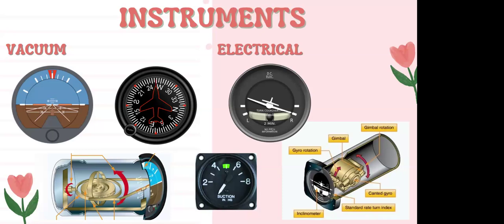So these gyros are rigid, and they're designed in a way to not fall over. But the way it senses your movement is because when you bank the aircraft, so you enter a turn, or when you pitch the aircraft, so a climb or a descent, it's essentially like pushing on the gyro. So you're pushing ahead, behind, on the side of, and that gyro is feeling that movement.